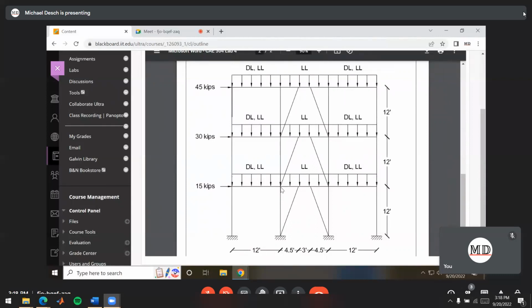And these are called eccentric bracing. They're eccentric because they don't cross the bay. If they make an X across the bay, it's called concentric bracing. But because there's a bit of a gap between these, they're called eccentric. Sometimes if they meet right in the middle, it's called a K brace or a chevron brace as well. But the one we're doing today is an eccentric brace.